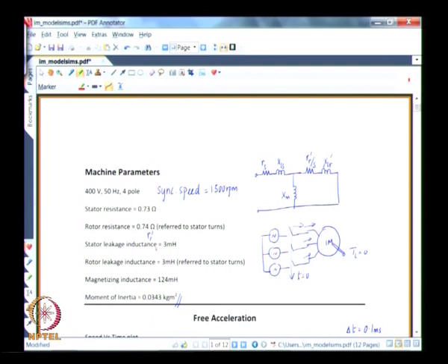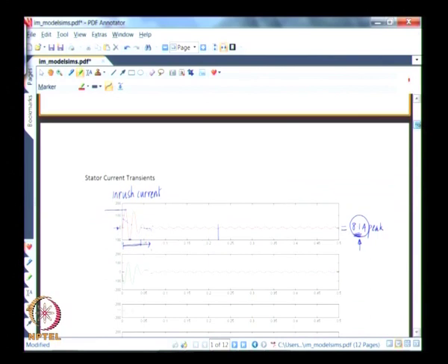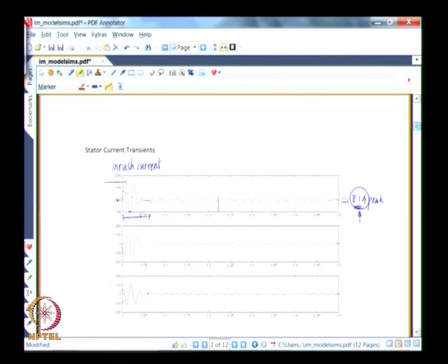and you are applying the phase voltage here. You know all the numbers, they are all given. So, try to solve for how much input current will be drawn, and you will find that the input current drawn is about 8.1 ampere sinusoidal, 8.1 ampere peak, that is the current that will be drawn. So, again we see that the set of equations that we have, once solved completely and run up to steady state, gives us the results that are exactly estimated by what you get from the equivalent circuit itself. So, this is the stator input current.